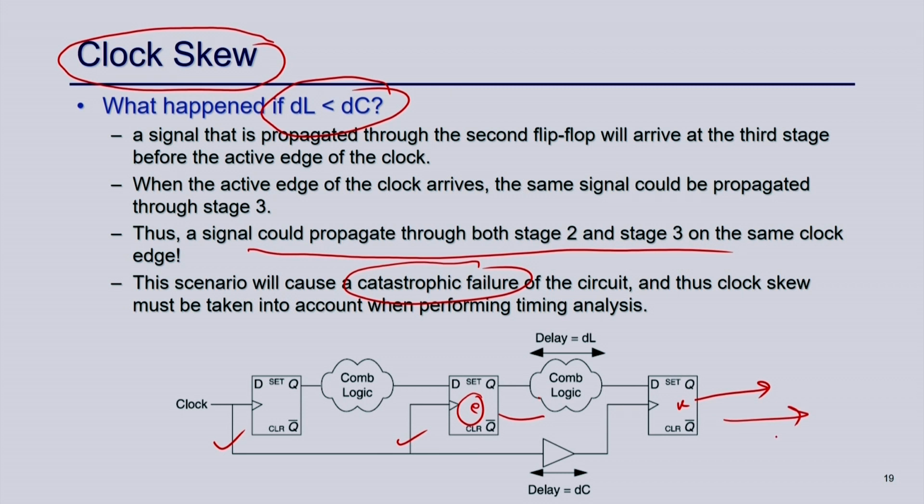So, whatever data is at the input goes to the output after 1 latency, 2 latency and 3 latency. If you have one data here, it will not be propagated here as well as here, because that is not allowed. Whatever the data here, it will come here in the next clock, and then it will come here.